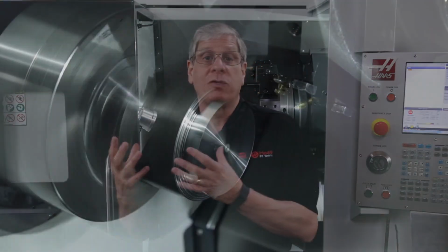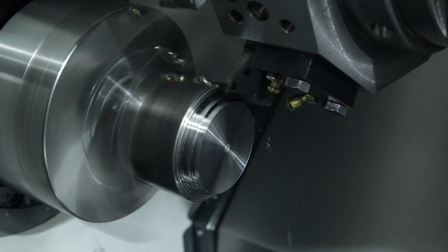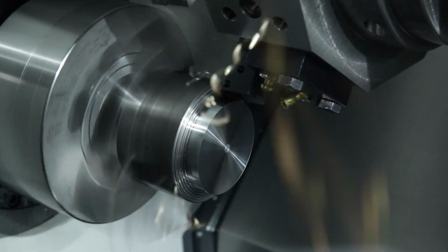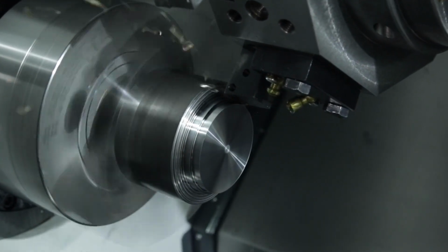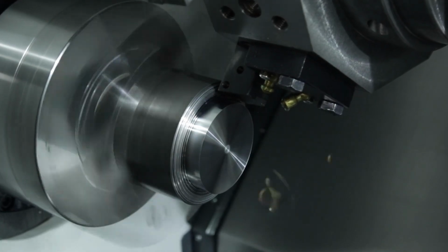Doing it this way means it doesn't matter what speed the spindle is turning, whether it's 100 RPM or 1000 RPM, the feed rate will remain .005 inches per revolution. This means as my rotating speed goes faster or slower, the distance the cutting tool travels will change with it. So I'm always cutting the same amount of material per revolution no matter what RPM I'm running.